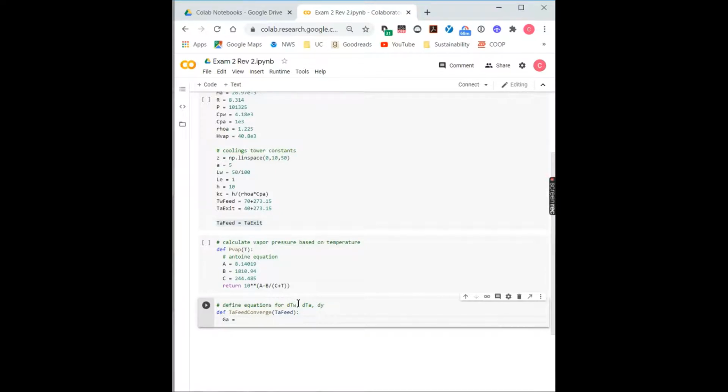So the mass flow will be the velocity of the air feed multiplied by the concentration of the air feed. So we have our velocity of 5 meters per second multiplied by the formula for concentration, which is P over RT, multiplied by our molecular weight for the air. So this will give us the mass flow per area of the air being fed to the column.